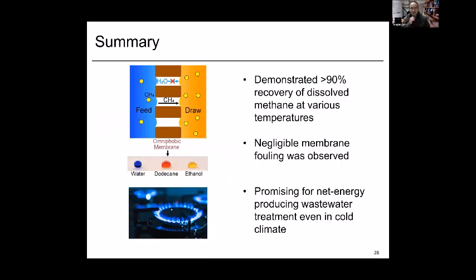So to summarize this part, we demonstrated more than 90% dissolved methane recovery at various temperatures, and we didn't see much fouling due to the lack of water flux across the membrane. And again, we believe that this is one way to produce net energy from wastewater, even in cold temperature regions.